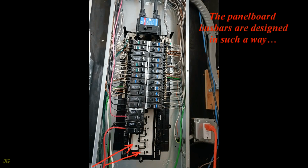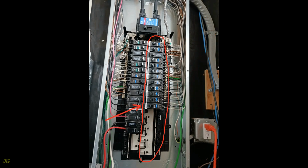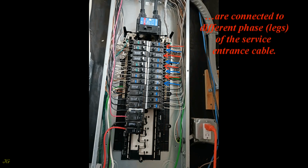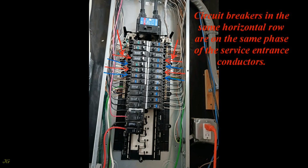The panel board busbars are designed in such a way that the circuit breakers installed side by side in a row, on one side or the other, from top to bottom, are connected to different phase legs of the service entrance cable: phase leg A, phase leg B. Circuit breakers in the same horizontal row are on the same phase of the service entrance conductors.